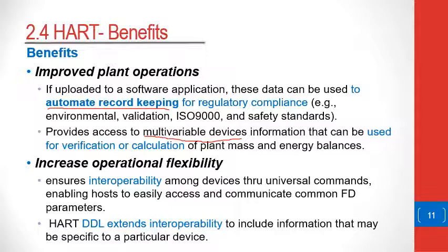It also increases operational flexibility, in the sense that each and every HART device understands the device description language, which means each and every manufacturer can write new functionalities using device description language into HART devices, and the configuration tool will be able to understand that. And it ensures that multiple devices can also operate and talk to each other easily, because now it has the implementation of universal commands, which each and every device must be able to understand.